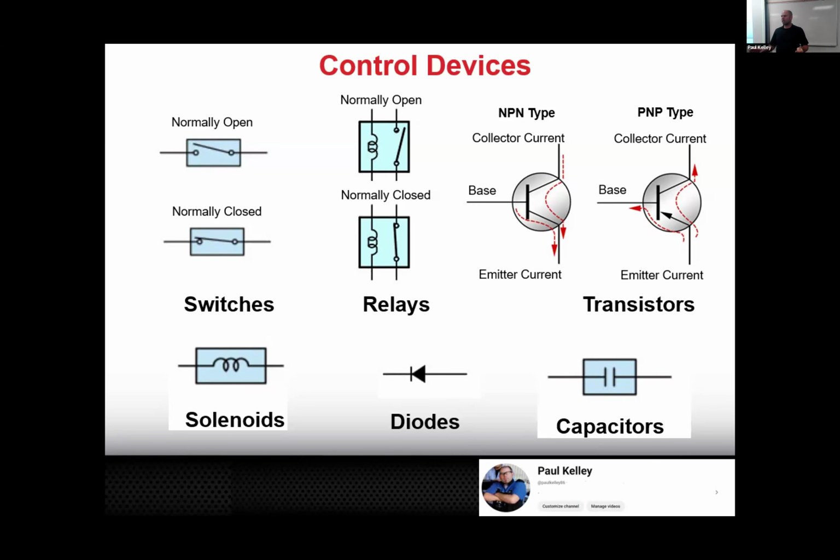The negative is, if you understood what I just said, normally when you want to disable airbags from deploying, you disconnect the battery and you're like, oh, the airbags can't deploy because the battery's disconnected. Well, wait a minute, there's capacitors in there. So a lot of times that's why service information will tell you, disconnect the battery and then wait this long: 10 minutes, 30 seconds, 1 minute, whatever.